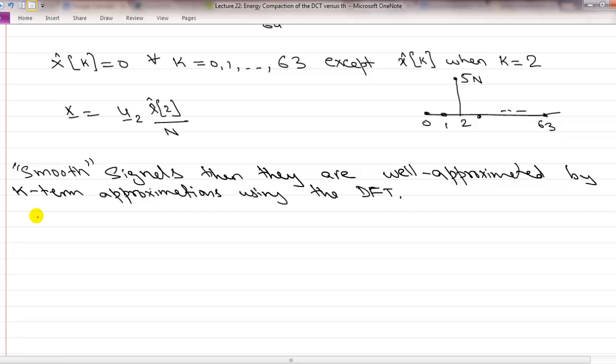And we won't go into the details. The discrete cosine transform at some level is closely related to the discrete Fourier transform, in that you can define it just like the way we define the discrete Fourier transform, by taking a signal and periodically repeating it and relating it to the Fourier series. But we won't go into that. I will just give you the direct definition.